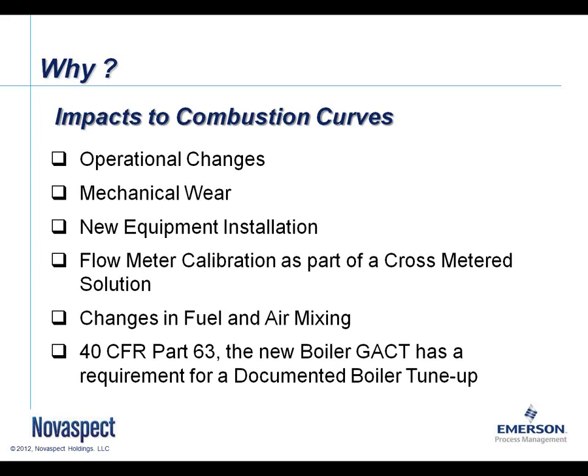And then, of course, more common things like mechanical wear. Something's happened to the damper drive. You've installed new drives or new valves. Maybe you're implementing your cross-metered system, so this is the first time that you've actually set up the combustion curves. Or any other reason that you may be trying to promote fuel air mixing changes. Maybe your burner guy has come out and adjusted burner settings. That would be a good time afterwards to run combustion curves, or during or while he's doing that.